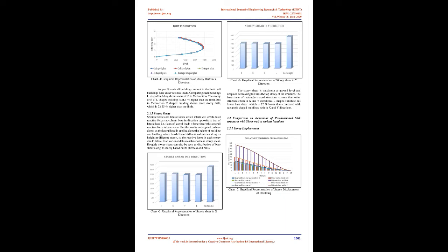2.1.1 Storey displacement. Storey displacement is the total displacement of a storey with respect to ground and is due to the lateral forces in x and y directions. The data of displacement of storey in x and y direction is collected for seismic loading from symmetric and asymmetric buildings. Chart 1, Graphical representation of storey displacement in x direction. Chart 2, Graphical representation of storey displacement in y direction.